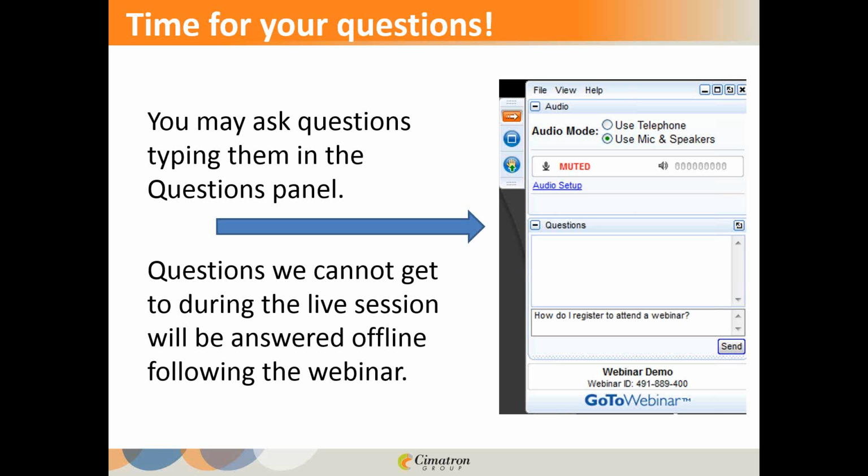Right. A couple guys asked kind of the same question. Can you account for process variables, forming speed, for example? Yeah, that's a good one. With a deep draw part, the slower you get, the easier the metal is to move. You're not likely to shear it so bad, that kind of thing. Right, and you're going to generate less heat. That part of predictive intelligence, I would say we do not have. We can't do that yet.